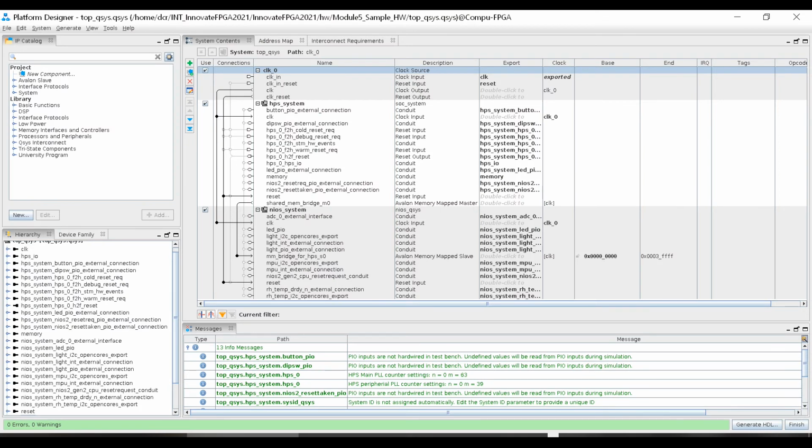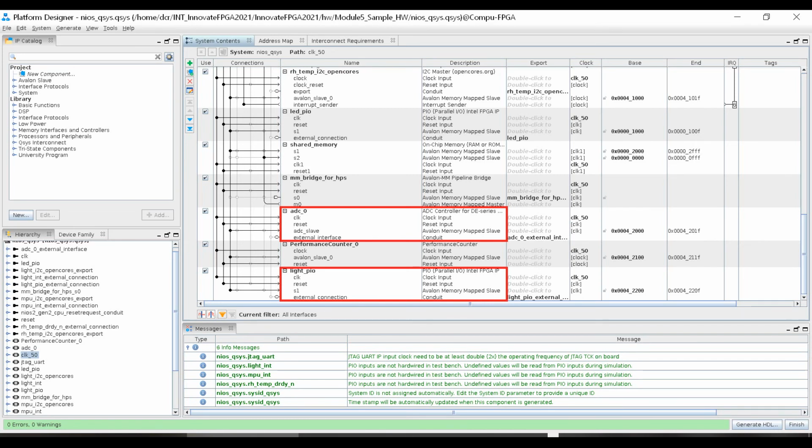This is a view of the Platform Designer tool available in Quartus. We have reused an example project from Intel to build our system where we have just added the IPs required for our application, in this case, an ADC controller and a GPIO to modulate the light used in the sensor with a 5 Hz square signal. Once we generate the system with the Platform Designer and assign the corresponding pins to the new connections, we are ready to go to program the Intel FPGA.